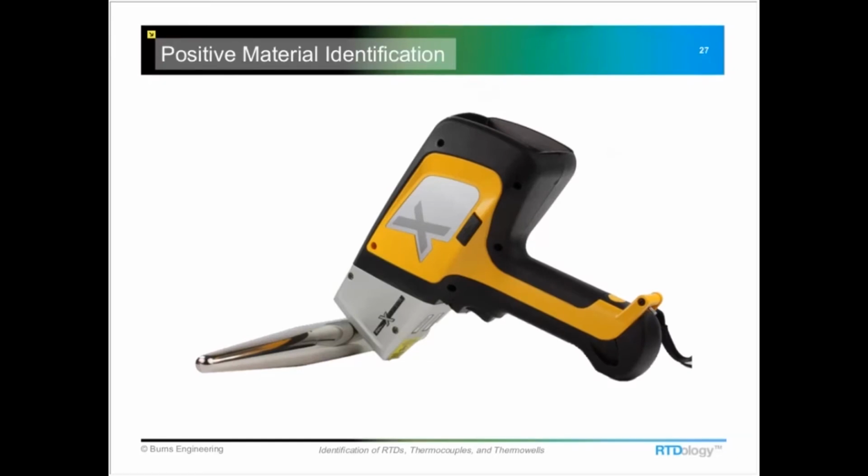And then if there's no other way to find out, there is a method using an X-ray fluorescence gun here to determine what the material is on that Thermowell, and we could potentially match it up with that kind of a process. I suppose another potential way is if you could determine what the material of the pipeline or the tank is, you could match it up that way too and just use the same material as the pipe or the tank.